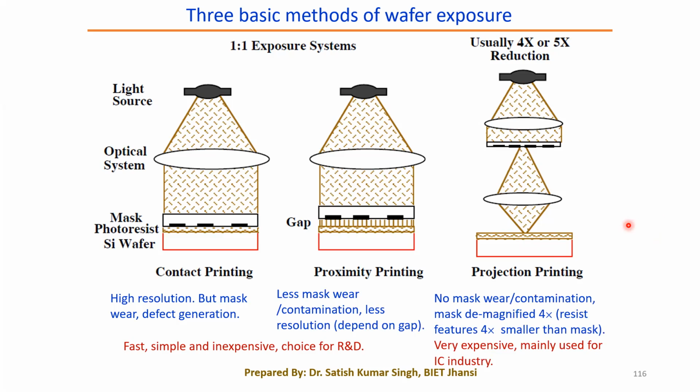Obviously, because the systems are not touching each other, as it is an optical system we are using for focusing the beams, the wafer and the mask are not touching each other. So there will be no wear and tear, no contamination, and therefore the defect density will be very low. But this system is very expensive, remember that this system is very expensive.